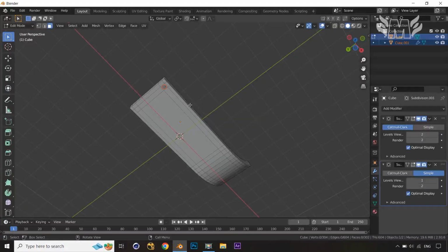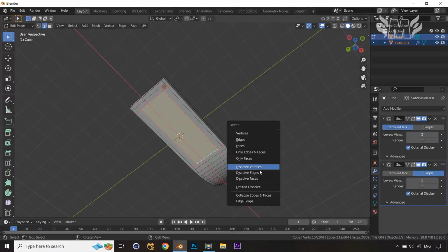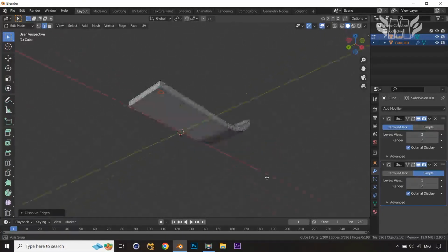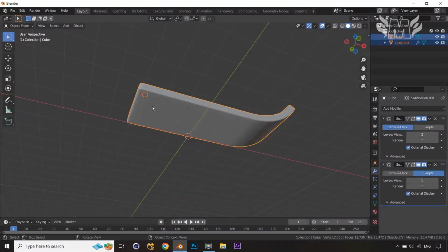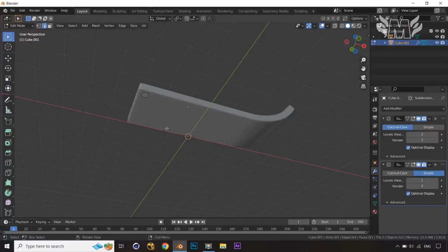Okay, then what I will do, I will just Alt this, press 2, Alt click, and then Shift and Alt, then Shift and Alt, and Shift and Alt, because we don't need the X, and dissolve these edges which we don't need. So okay, it's good enough. Jump into the object mode, select this object and this object, jump into the edit mode again, press 1